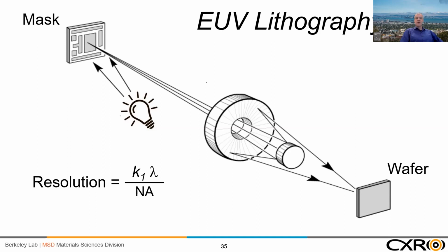The silicon wafer is coated with a chemical film, much like old school film cameras, where you had this chemical on your plastic film, and that recorded the image. In this case, we record the image on this film on the silicon wafer, and then we use etch machines to etch that picture into the silicon wafer and make a working electronic circuit.